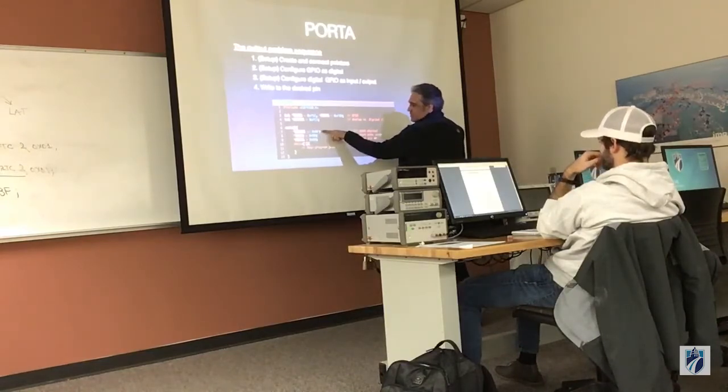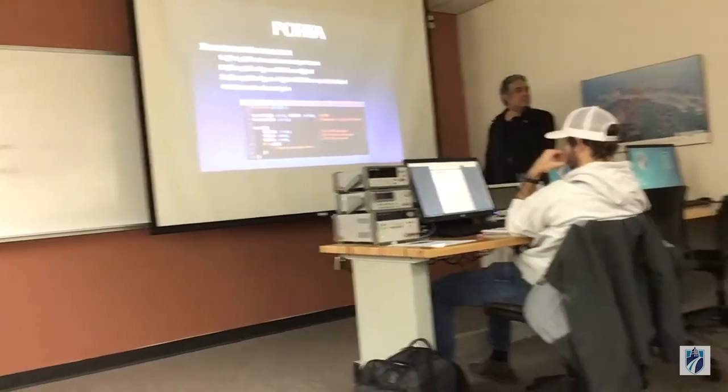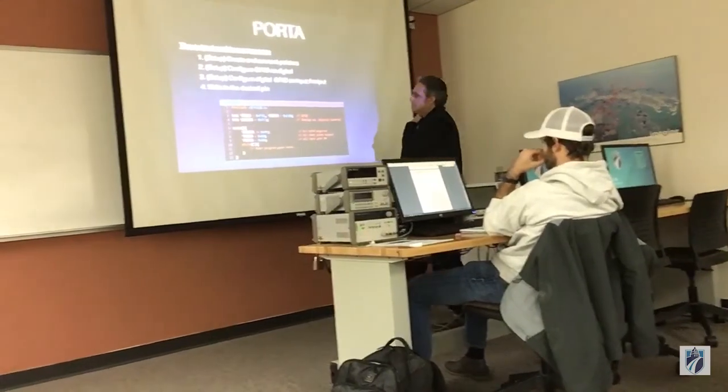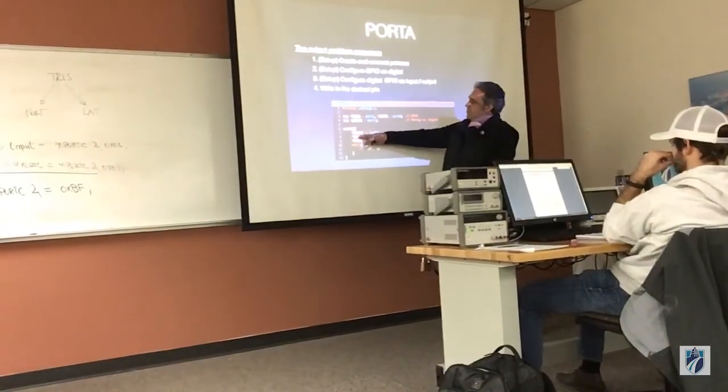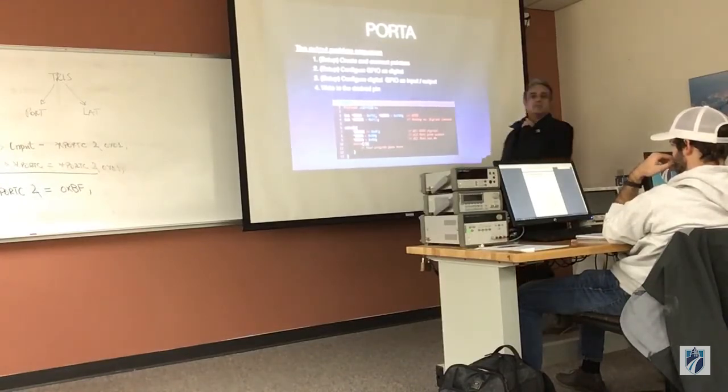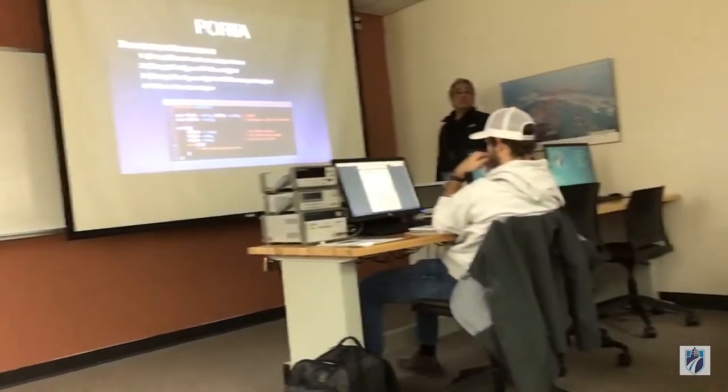Make it digital, make it output, force an output. See the sequence? I actually make it a digital bit, then I make it an output, then I write voltages to it. So that's the sequence that you have to follow.